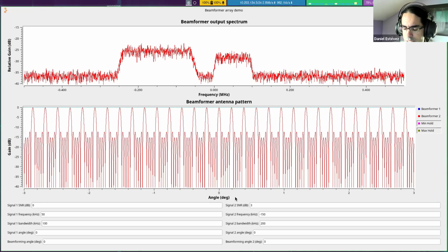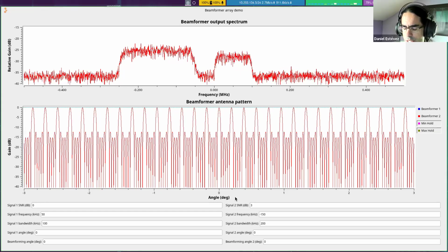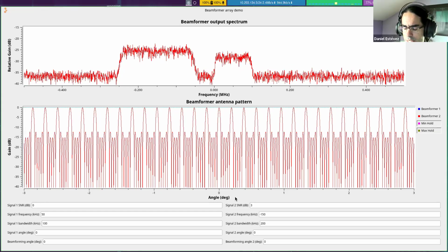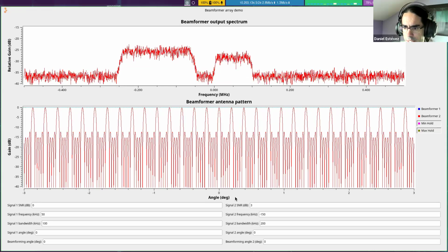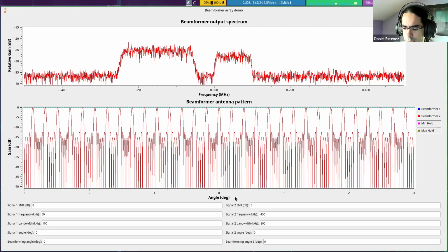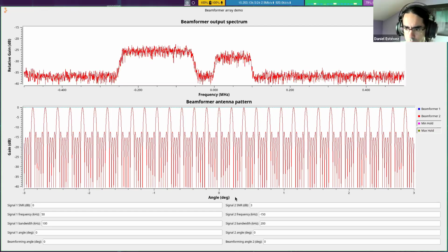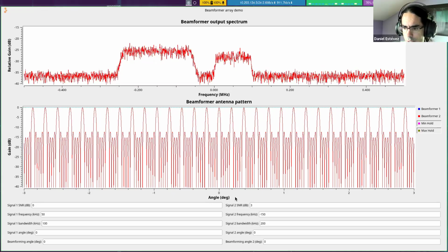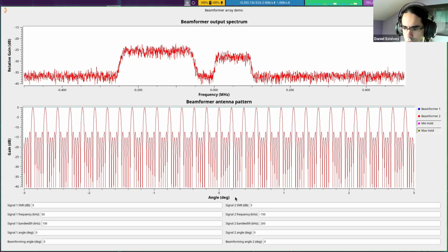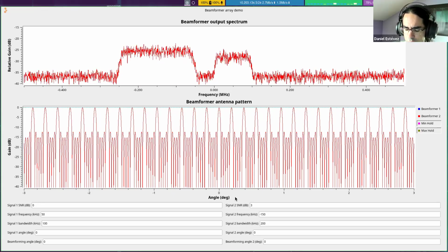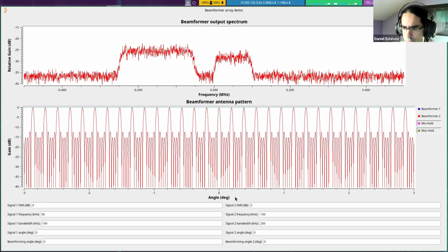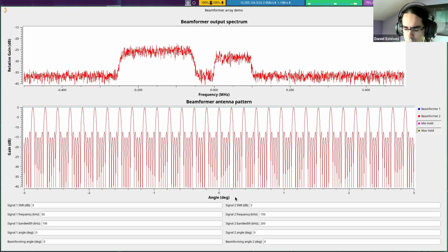And there's an analogy which Steve makes, and I think it's a great analogy: if you have a very large single dish, you can get very good images because you just sweep your dish all over the sky and you basically scan your pixels. Then you can imagine if you are punching holes in the dish, you get a weirder antenna pattern which has some grating lobes, and so your images are not so nice.